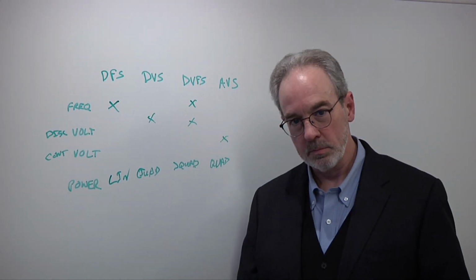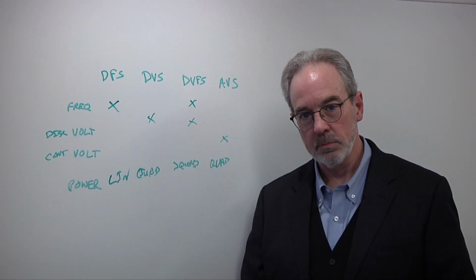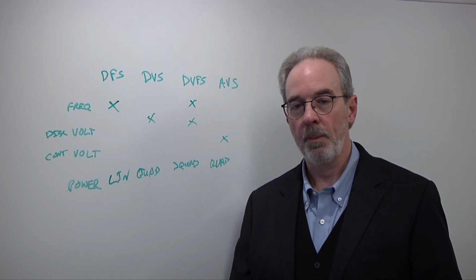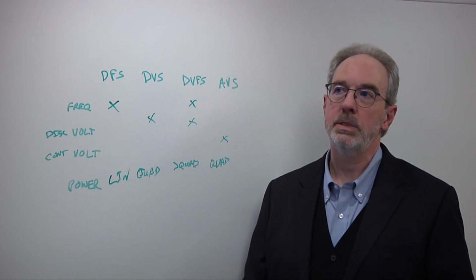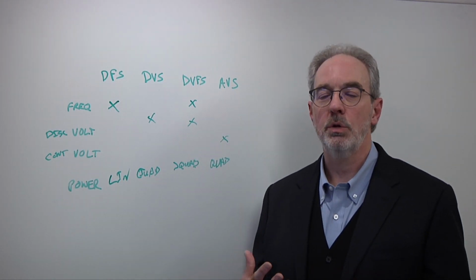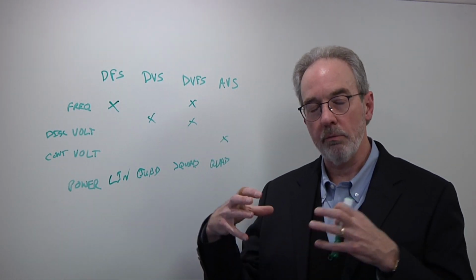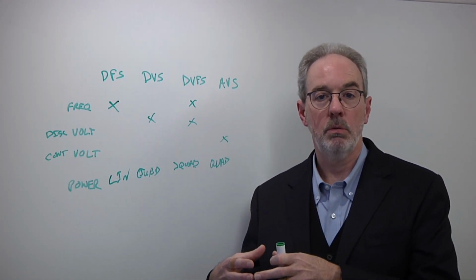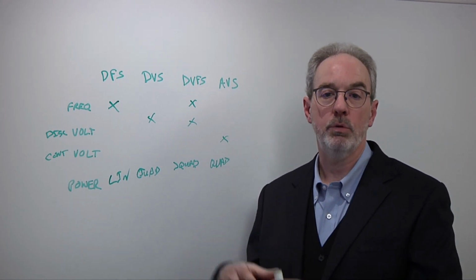So now that you're trying to move this down to the mainstream designs, what do you have to worry about that you didn't have to worry about before, and where do people go wrong? Well, I think one of the key things is that in order to enable this kind of power techniques, you have to consider a case where you're driving your voltage manipulation, in particular, from an external to an internal factor. In other words, we're talking about on-die voltage regulation.